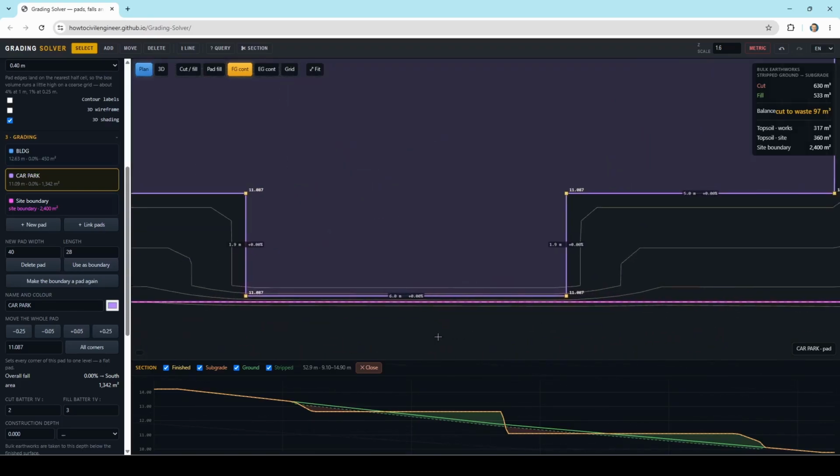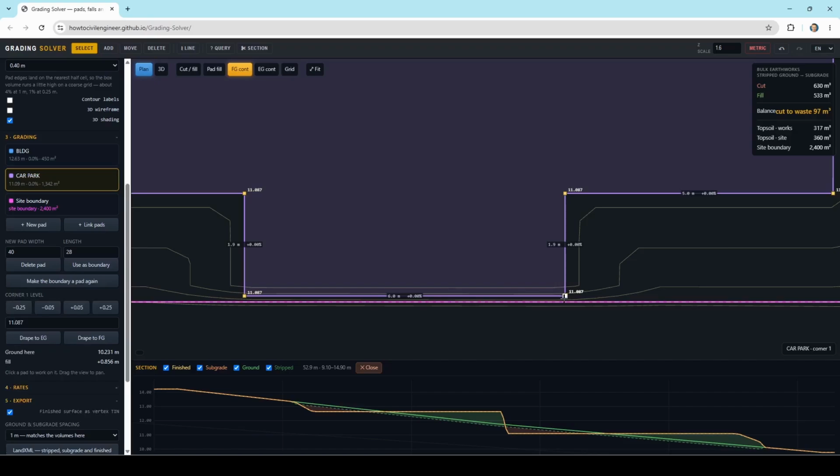And you'll notice this line work is not connected to the line work here. And that's purposeful because Civil 3D users know, and 12D users, Bentley, it's not truly 3D, it's 2.5D because you can't have two Z values at the same XY value. So there's usually an offset, as you'll see as we go here. But if we take this point here, we can drape to existing ground like that.